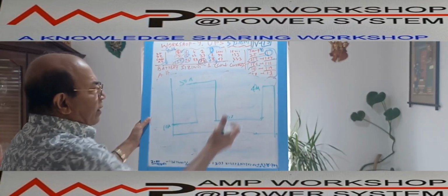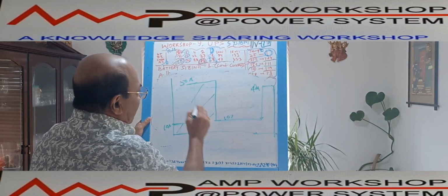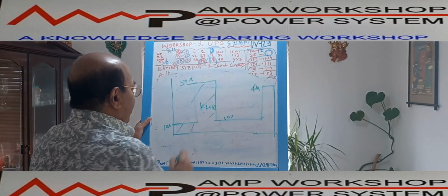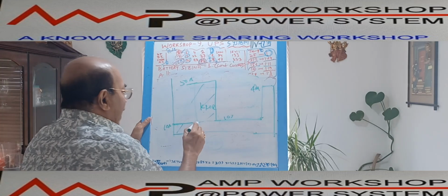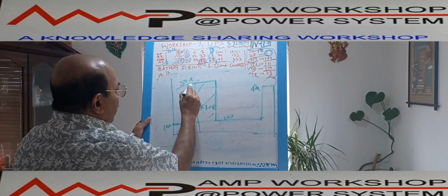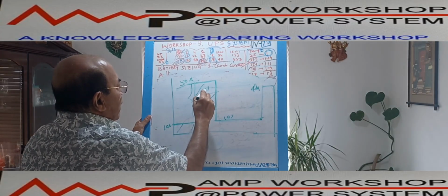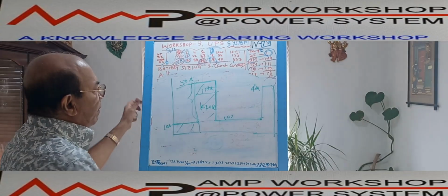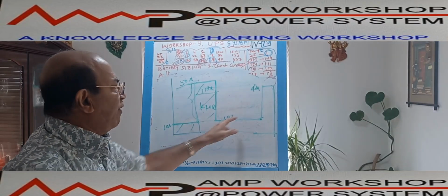In that case, we cannot go by that calculation, because you know what the major difference is over here? For each part, the rate of discharge factor will be different. Here the battery is maintaining 10 ampere up to this time. But at this time, what is happening? Suddenly the current goes up, so it has to deliver 40 ampere differential. That current maybe is for only 1 hour. So for 1 hour discharge at 40 ampere, we have to calculate from the table how much ampere hour is required for this.